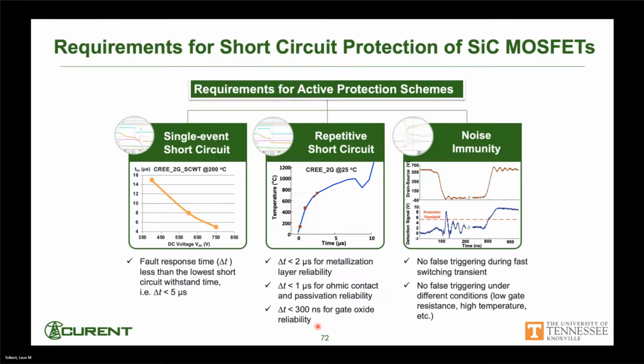The other thing we worry about is noise immunity. You do not want to have any false triggering here, meaning you don't want it to think that you had a short circuit when you're turning something off or turning it on. And so you really want to have some sort of capability or delay to make sure that you have a short circuit and that you're not interrupting things when there really wasn't an issue. It was just some noise.